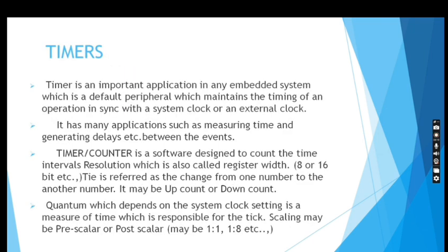Timers. Timer is an important application in any embedded system, which is a peripheral that maintains the timing of an operation in sync with a system clock or an external clock. It has many applications such as measuring time and generating delays between events. A timer or counter is designed to count the time interval, with a resolution register of 8 or 16 bits, etc.